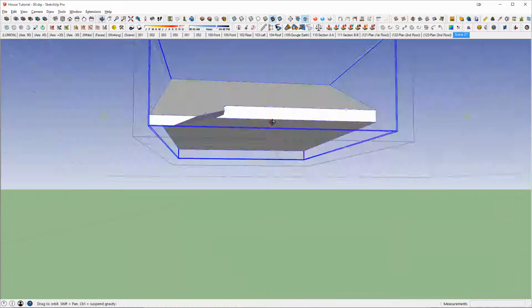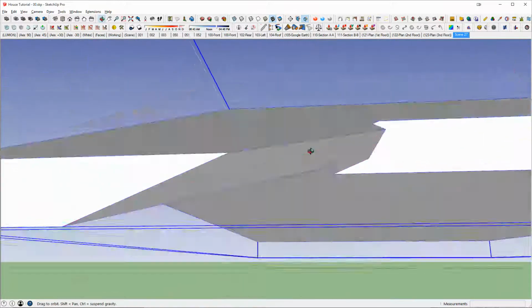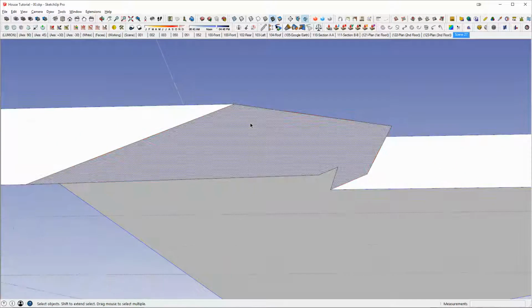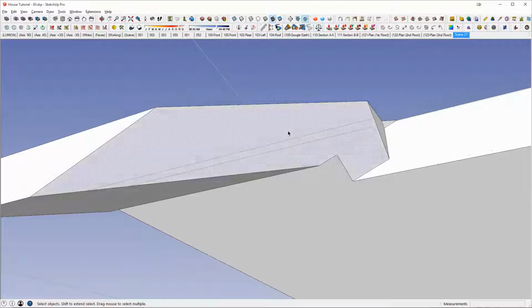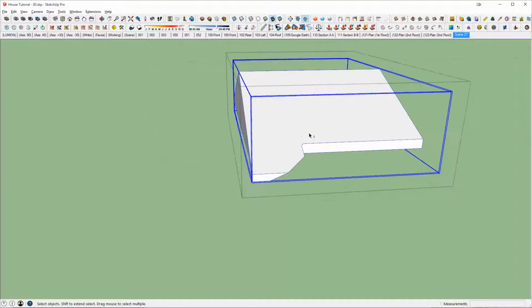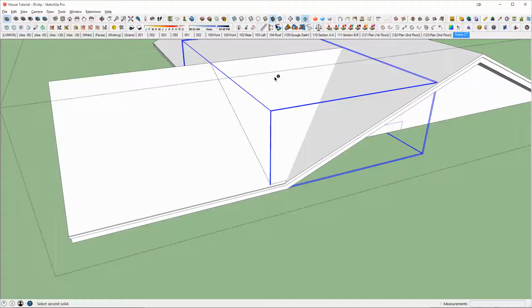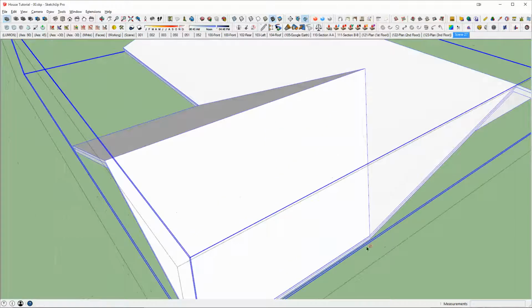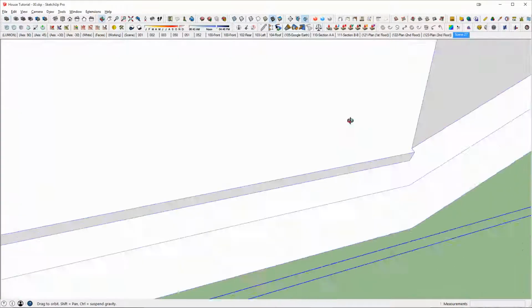And we'll run F2, and there we go. It's telling me there's something happening here. Maybe there's a double face. Yep, there was. So I deleted one, which means there was another one there, and we got rid of it. And there's your solid tools in action, and how to use them to your advantage.